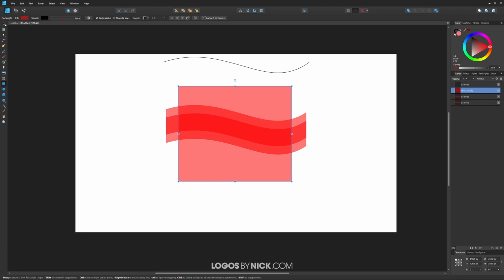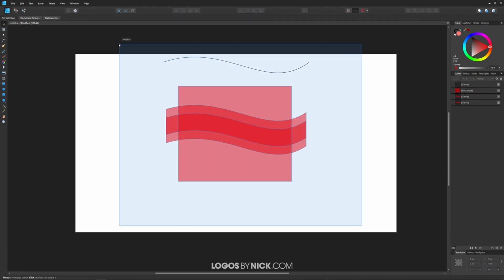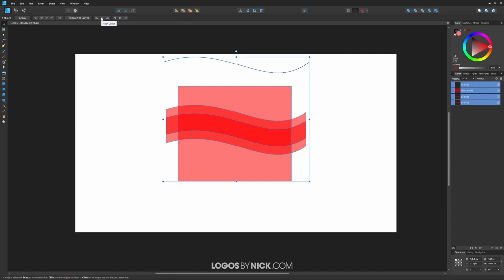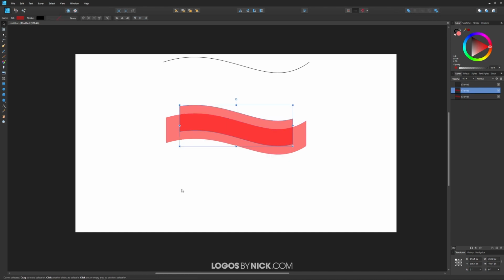And let's go to the select tool. Let's select everything. And again, we just want to make sure it's aligned vertically like that. It's very important that we have these objects aligned on the vertical axis as we're doing this tutorial. Okay, so once you've done that, let's click off of it to deselect. Let's take this top little shape right here, this top ribbon, hold Shift, click on the rectangle on top of it, and then we want to create an intersection from it. So we'll come back up here to our little Boolean operations, and I want to click on this intersect just like that.